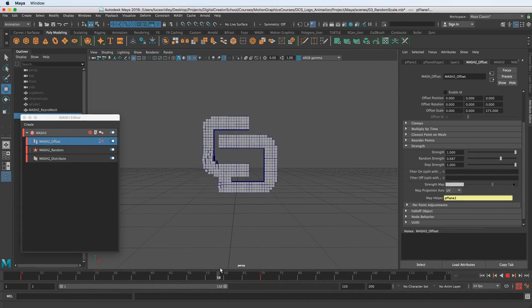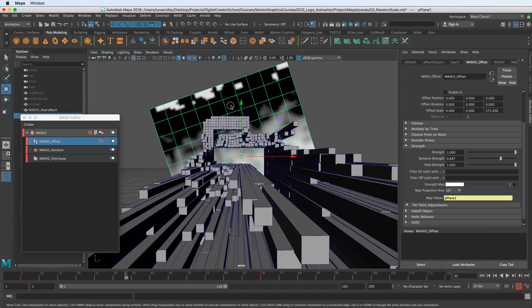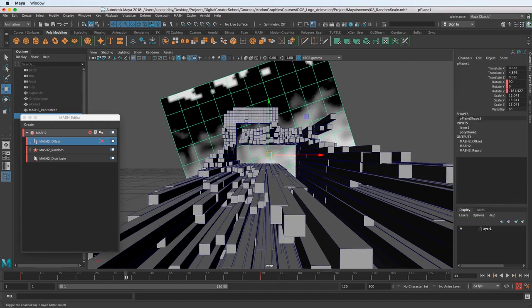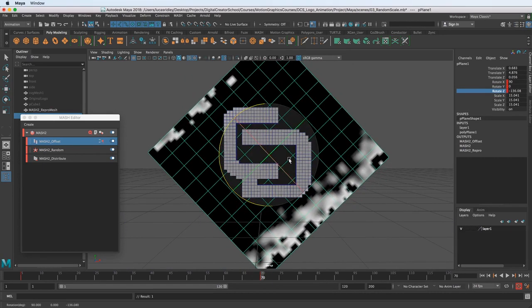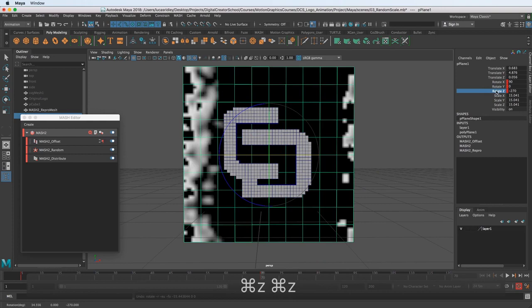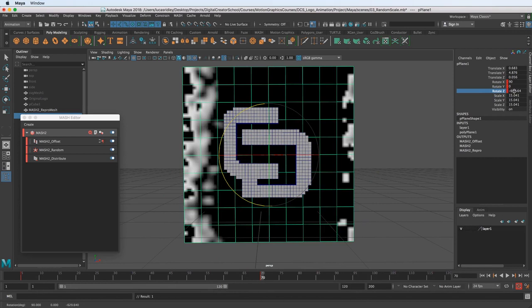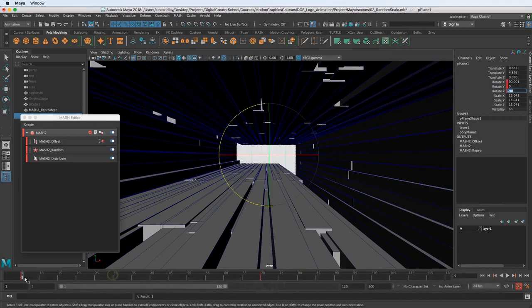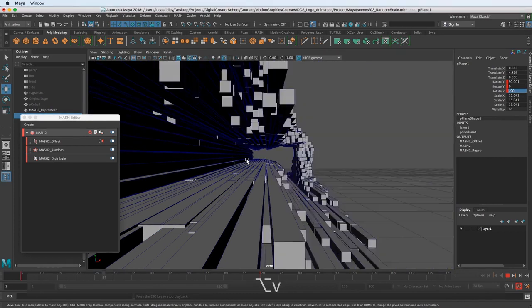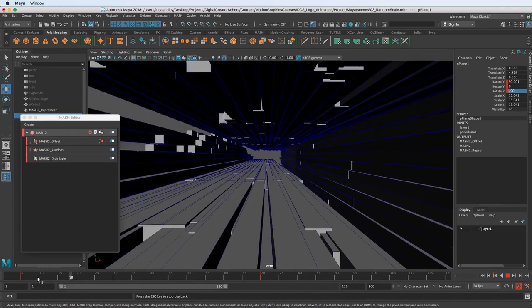And again, depending on how you want this to look, you could have it spin twice as much, right? Let's go to this keyframe, and instead of 270, oh wait, we're actually adding, let's see, yeah. Let's just go all the way around, do something super crazy. 630. So now it's really going to spin around. So I'm going to hit Alt-V to play. Yeah, that looks pretty cool. So we're just adding more rotation there.